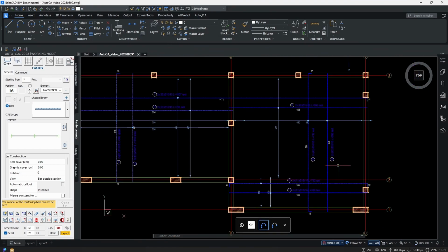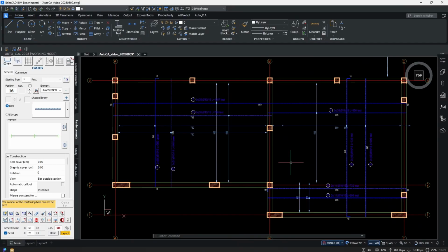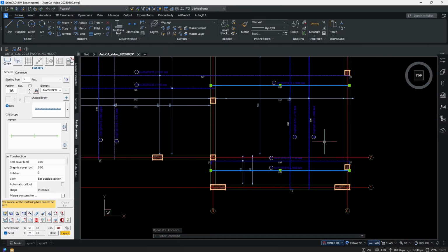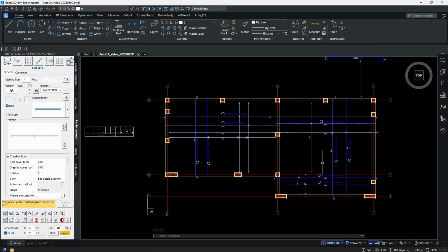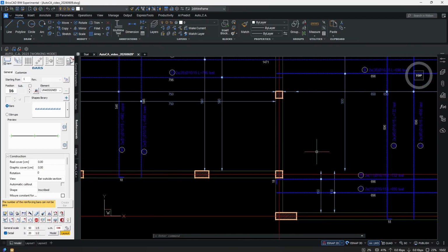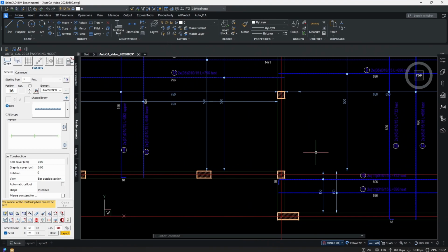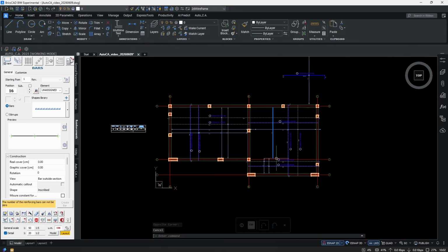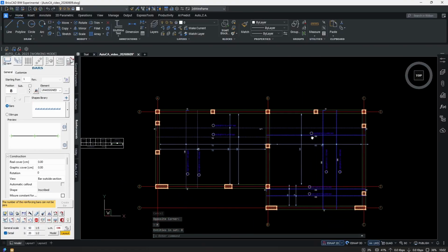So now what we did was we copied a lot of bars and changed their shapes, but we left two bars being identical because it will be important later. Now let's look at mass modification. I suppose we decide that all these bars should have a different spacing or a different diameter. Instead of editing them one by one, we can update all similar bars simultaneously, as we saw earlier with these two bars. But now we will do it on a bigger scale.